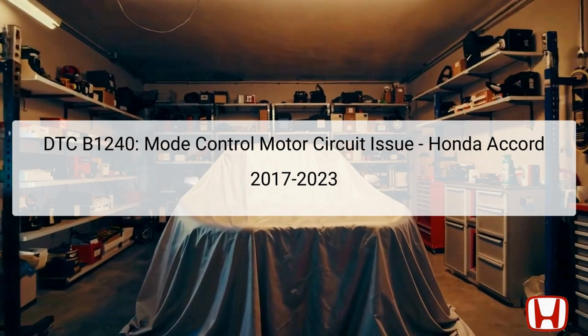The DTC B1240 is an indicator of a malfunction within the mode control motor circuit, which may involve the linkage, door, or the motor itself. This error directly impacts the vehicle's climate control system, affecting its ability to properly direct airflow and temperature throughout the cabin.